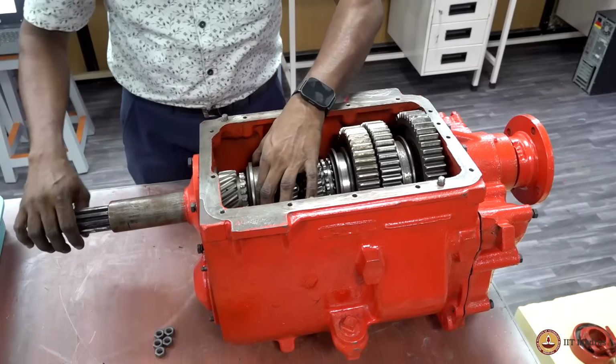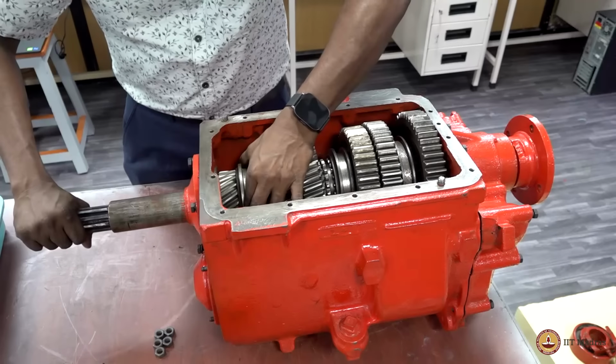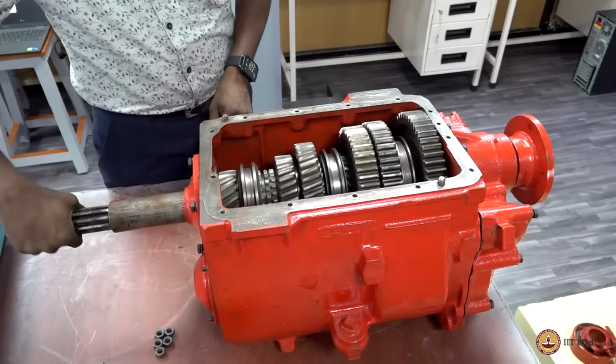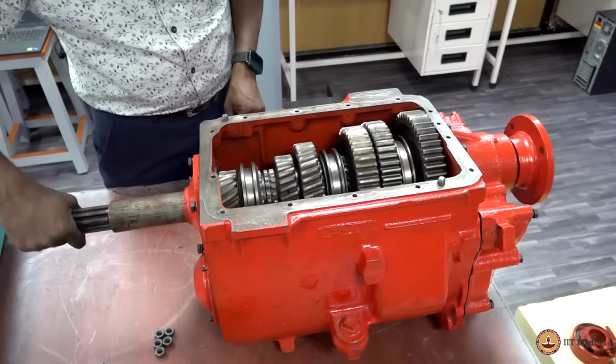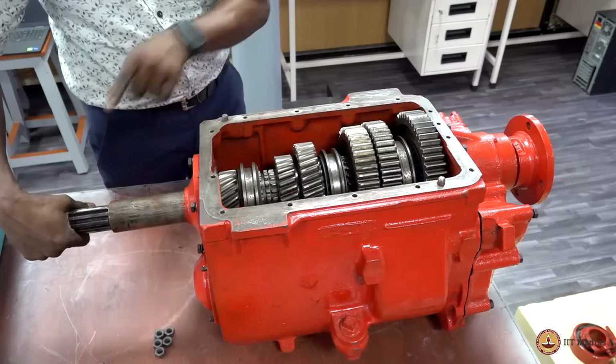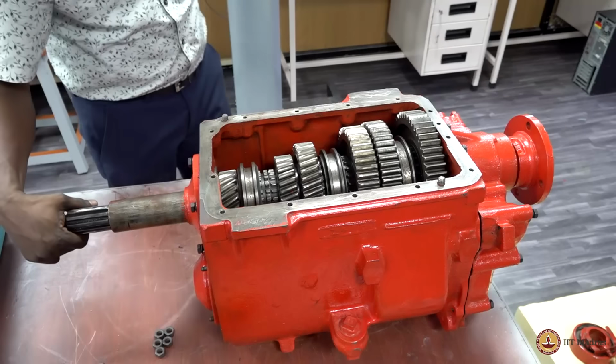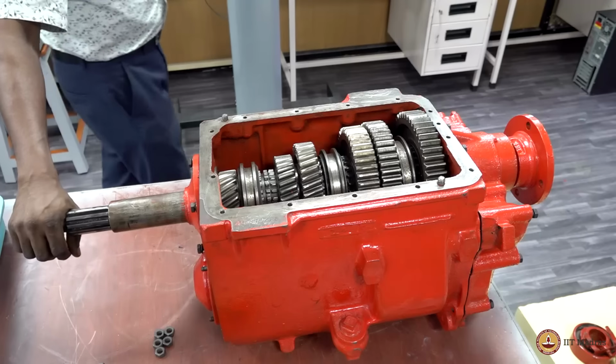Likewise, I engage the fifth gear now, the direct drive that couples. So now the marks are at the top. I made 1 complete revolution at both the input and the output shaft as well. So the fifth gear ratio is also met.